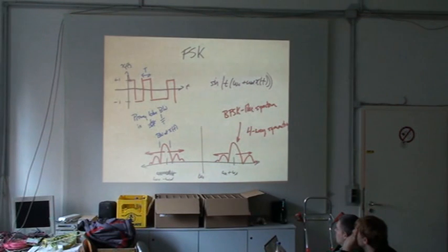But over here on the positive side of the spectrum, what we see are two BPSK-like signals sitting around some center carrier. The reason they both look BPSK-like is because each one of them is just being turned on and off pretty fast, and that's like BPSK with a DC offset. But you have these two BPSK-like spectra around some center frequency that you're not actually using.